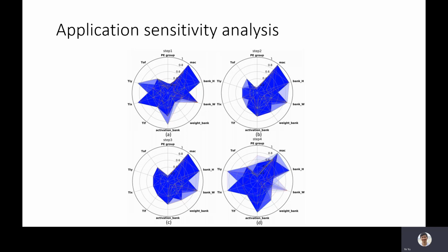We can see that reducing the feature map size of the convolutional layers impacts the loop tiling design variables. Smaller tiling sizes are preferred for better performance. Reducing the feature map size while keeping loop tiling variables unchanged will lower the efficiency of memory transactions. Thus, the value of loop tiling variables is also reduced.